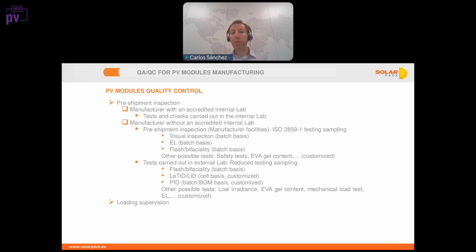In this case, in my opinion, it would be fine if we request test on cell basis, although you can also customize this test on batch basis or a certain quantity of tests for a project or whatever. Then we have the PIV, and again, this test should be requested on a batch basis or bond basis, or if you want to customize this test, again, a certain number of PIV tests for your project, you can do like that also. I think that all these tests should be carried out in an external lab.